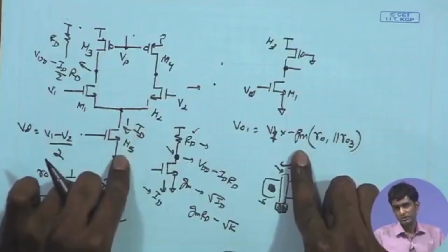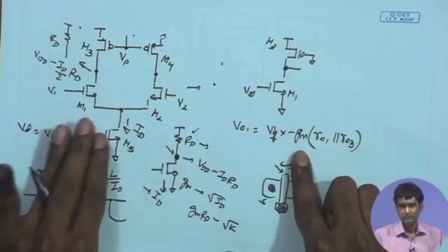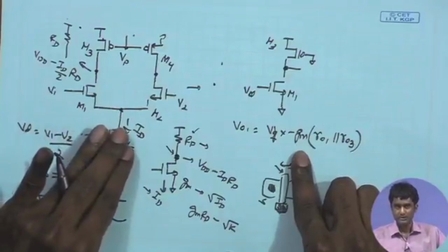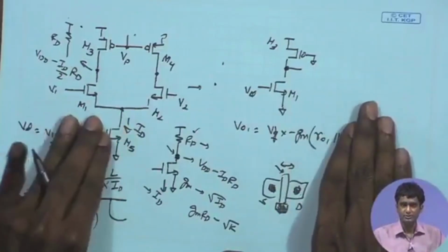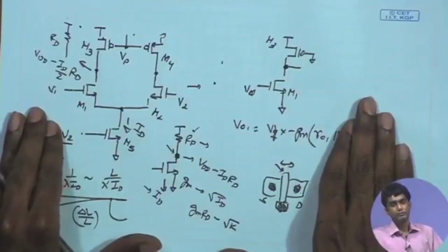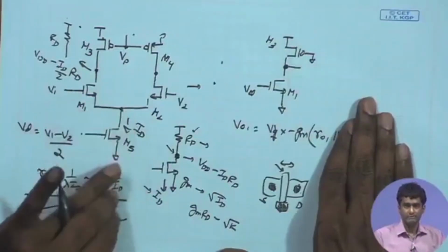So current is a value that you can control much better. When you are forming current mirrors, one side has the reference current, and the transistors forming the mirrors can also be matched. Two NMOS transistors or two PMOS transistors can be matched very well by appropriate layout techniques, and therefore you can have current defined in a very accurate fashion.